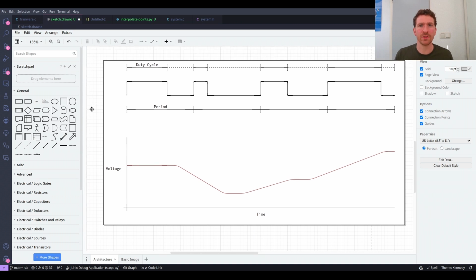There's a lot of theory that goes into this kind of stuff, right? You know, understanding the Fourier transform and the fact that square waves are actually made up of infinitely many sine waves of different frequencies, and that you have to add up a bunch of high frequency sine waves to get these nice clean square edges. Understanding that that's the actual nature of any signal that you're talking about. This is not just one way of viewing it. It's really that every signal is actually composed of these fundamental building blocks. Then you understand that this actually contains a lot of high frequency components.